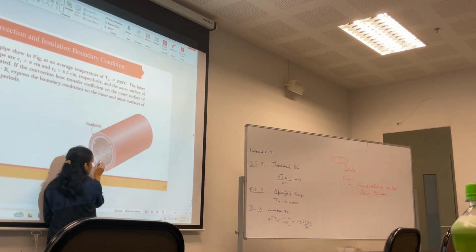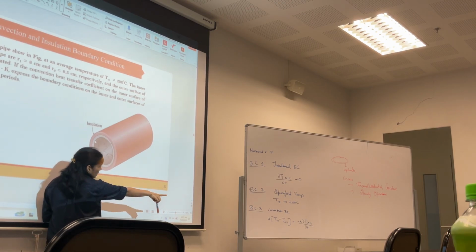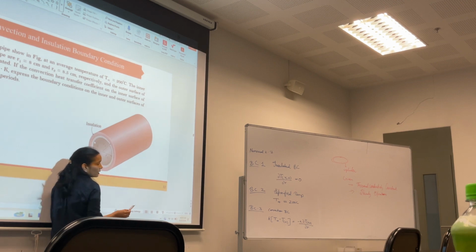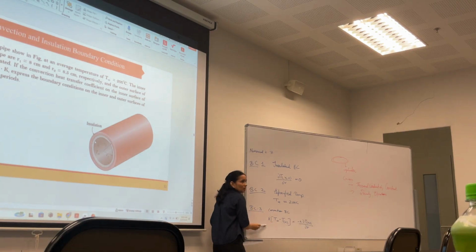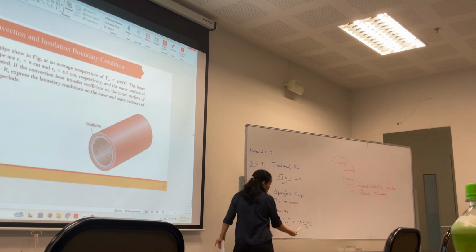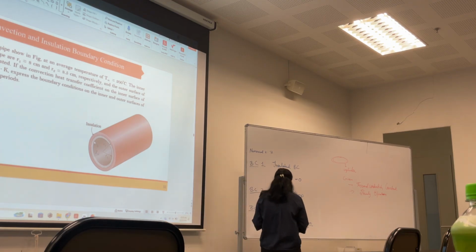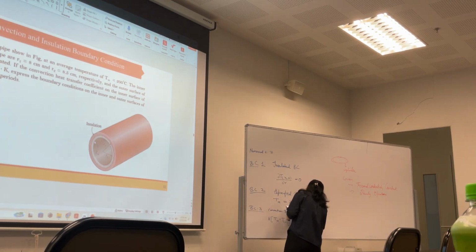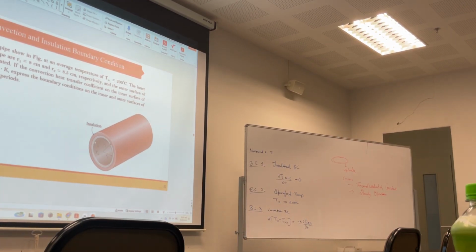Heat transfer is by steam, it's flowing from here to here by convection. T infinity to this, let's say T R1. From here to here it's a solid, so conduction only. This is the formula for convection. This is the formula for conduction. Be very careful with the coordinate R1. R1. R2. Sorry, it's going to be R1.